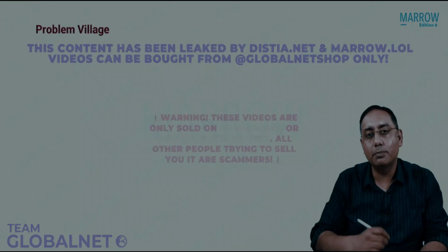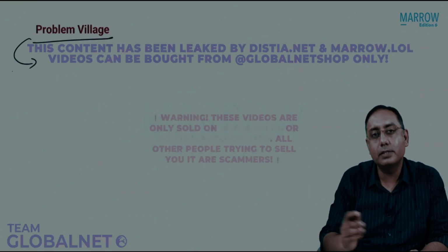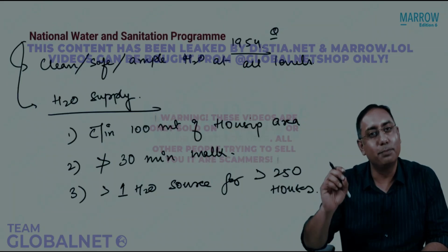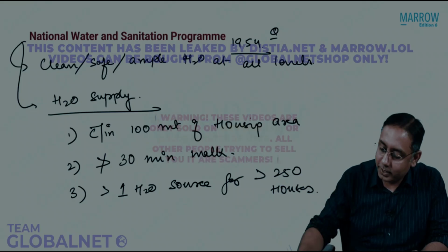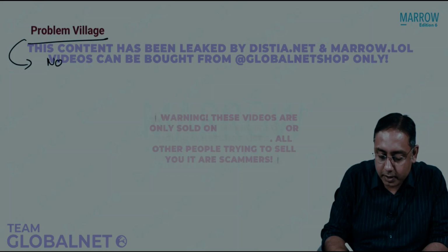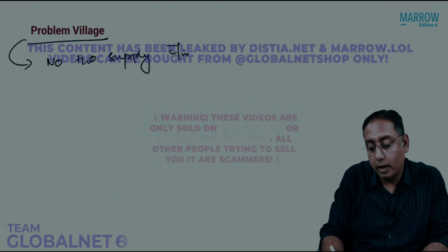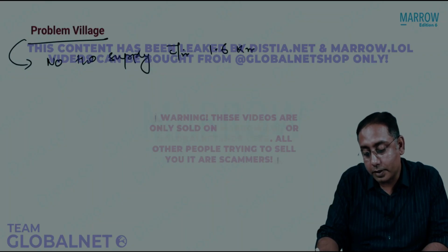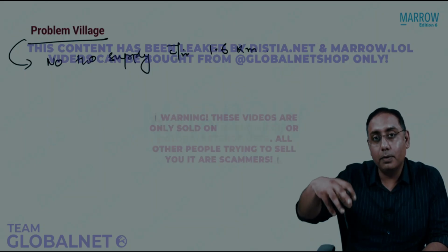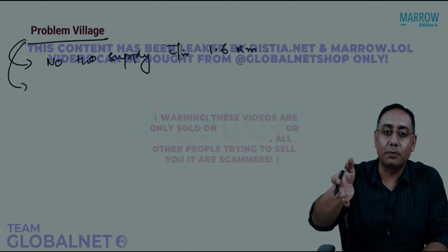Based on this, we have something called the problem village. What is a problem village? A problem village is a village which is a problem for the National Water Sanitation Program. So what are the problem villages? A problem village is a village in which there is no water supply within 1.6 kilometers. So that is the main problem village right now. The focus of the program will be on these problem villages.